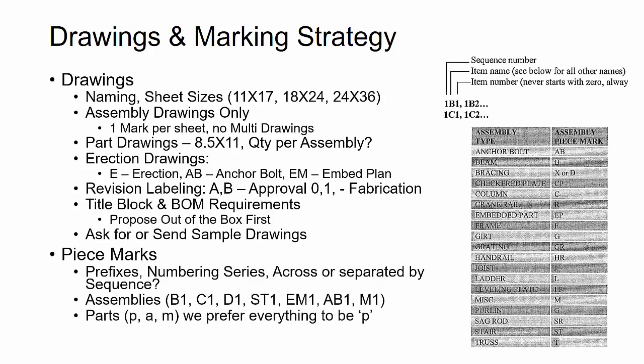Then, of course, looking at piece marks. Stairs are a lot more complicated as far as the number of pieces involved, especially some material parts compared to, say, a standard structural member. So really making sure that you have all of your prefixes and your numbering series and names of parts and items in the model set up correctly will be really important. So that way you can have that stuff set up by the time you get to shop drawings, you don't want to be dealing with or catching any of those issues, so you don't have to go back into the model and fix things and then update your drawings.